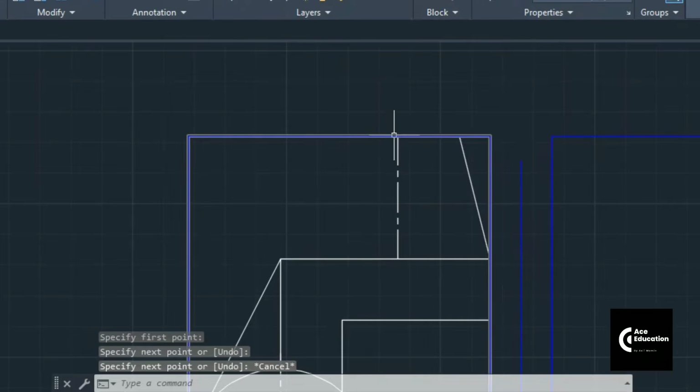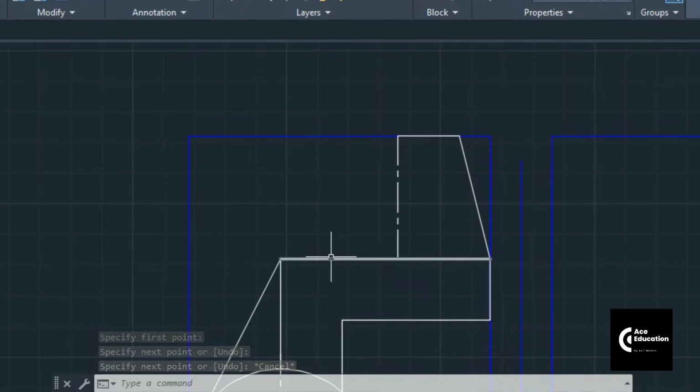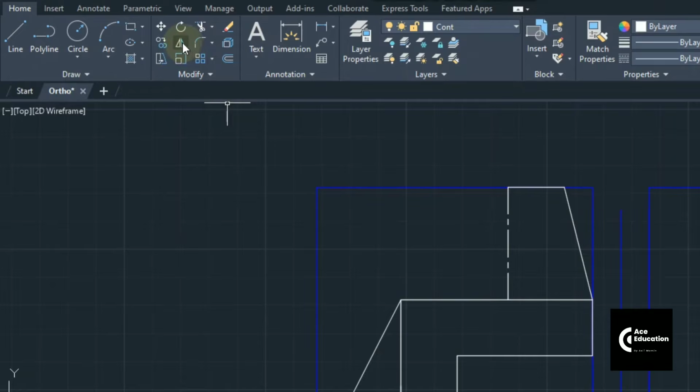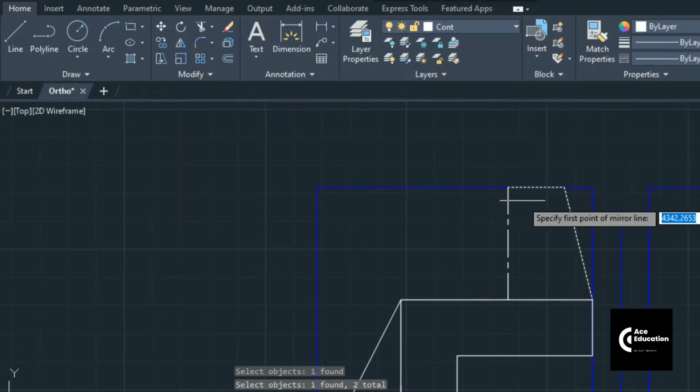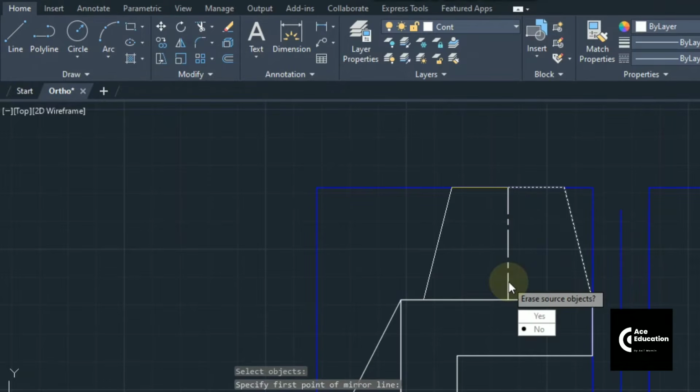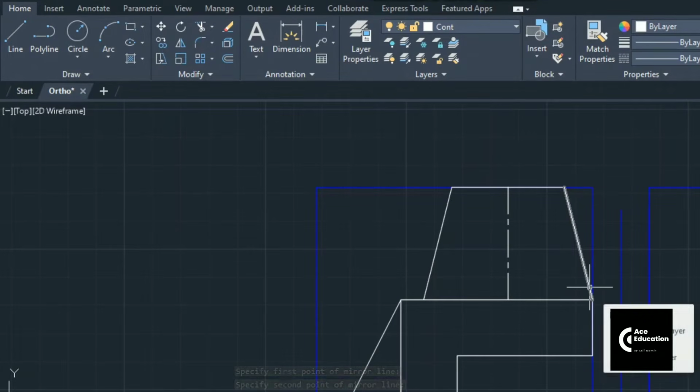Similarly, we can draw 20 mm on the left hand side, but here also we must have a 30 mm distance. So you can draw a 30 mm line again and connect this one, or you can just mirror these lines. Go to the mirror command. This one is the mirror command. Select the lines which you want to mirror. I'm selecting both the lines. Then just right click and left click on any 2 points on this vertical line, because we are considering this line as the mirror plane. Then press enter. You can see here the frustum of cone has been made.